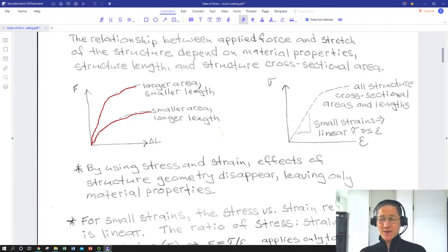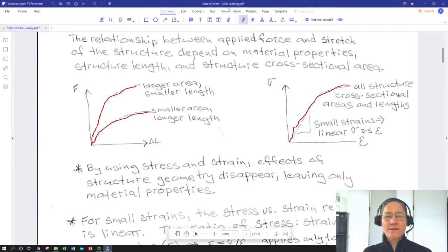But to get at that material property and look at how it affects the force versus elongation relationship, we have to have a way of getting rid of the geometric factors. And as it turns out, if we plot stress versus strain instead of load versus elongation, all of those geometric factors effectively cancel out. We could write mathematical expressions showing that they do, and we're left with only the effects of the material properties. And so this is perhaps the stress-strain relationship for that particular cylinder, and it no longer is a function of the geometry.